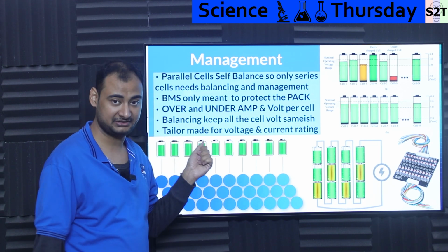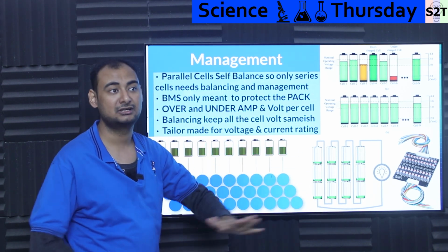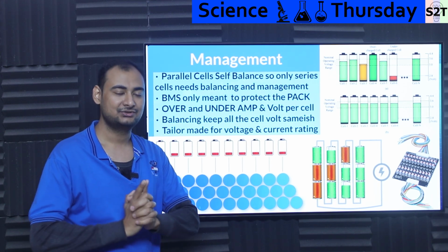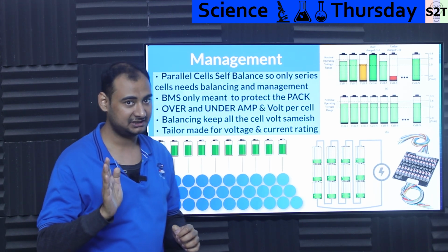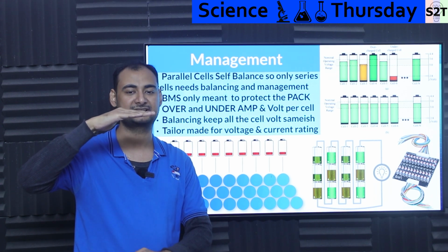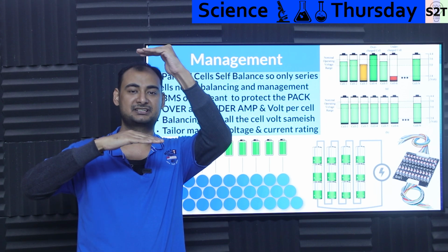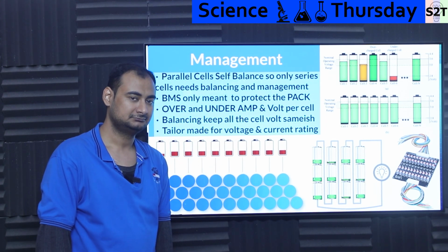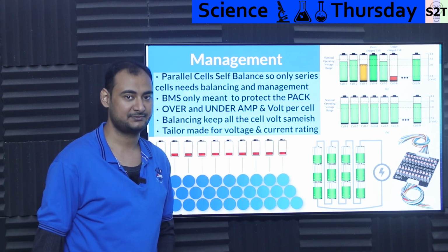It's a tailor-made system. You're supposed to have a balancer if you want long life. You're supposed to have a BMS that is matched properly so it does not put strain. Let that be very clear. If a cell can go to 100 amp of surge, you never put a BMS that is like, oh, I'm here. You put a BMS that is here. It's like, oh, I will never let more than 50 amps touch you. You always have to do that. Only then you can have lifespan.